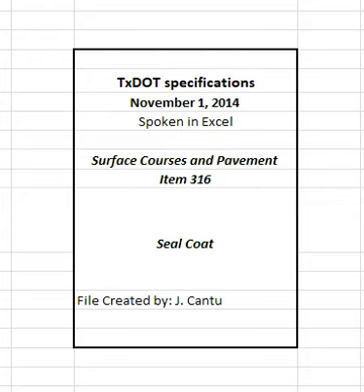4.4.2 Polymer modified asphalt cement temperature limitations. When using materials described in section 300.2.2, polymer modified asphalt cement, apply seal coat when air temperature is above 70 degrees Fahrenheit and rising. Do not apply seal coat when air temperature is 80 degrees Fahrenheit and falling. In all cases, do not apply seal coat when surface temperature is below 70 degrees Fahrenheit.